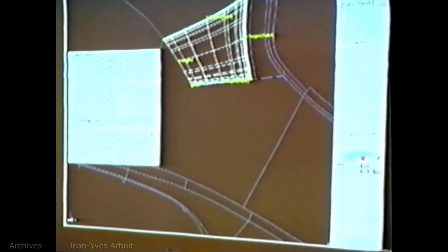You got to rebuild every edge. You got to go up and rebuild edges, I think. I think not. I think I just have to have the max spans go down to 0. Okay. So now it's a 3x3 patch. I can say make it a 5x5 patch. Still going to try and enforce that continuity based on the tangent planes, but now I have more control over what the degree, what the spans are across this surface.